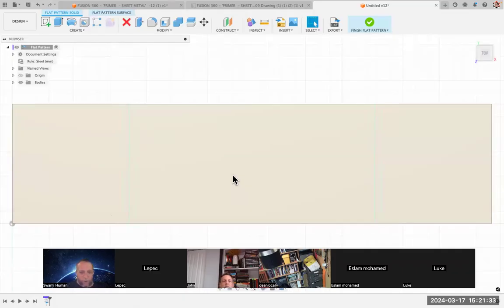That is to say the unfolded thing with the slightly different dimensions, so that when you bend it, through the process of bending and how that shapes and deforms and resizes things, it turns out correct. So if our original sheet metal object is correct and follows the constraints of reality for constant thickness around the bends and all the other things it needs to have right, you will get a valid flat pattern.